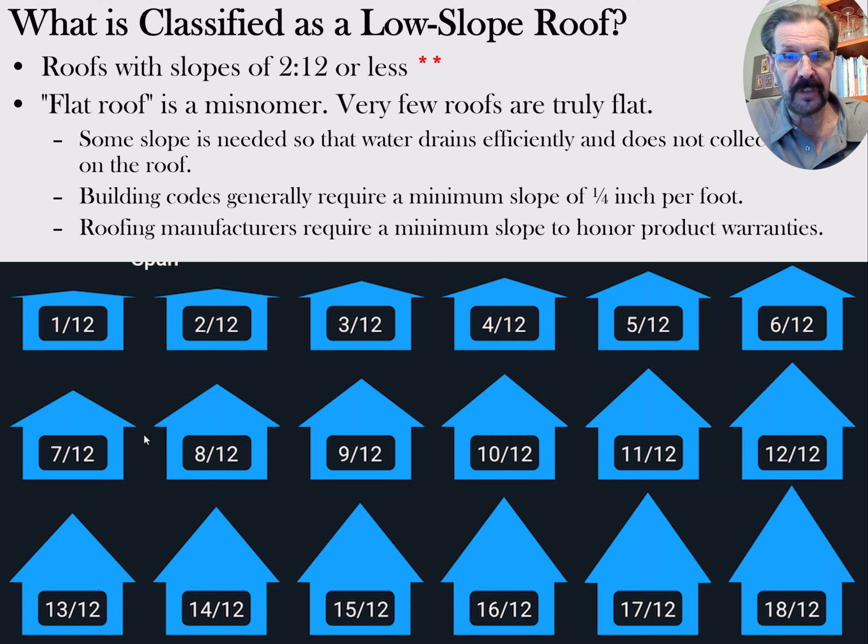Typically with shingle roofs on anything less than a 4:12 slope, you do have leakage. Unless you just put in a good solid single-ply roofing down as your really, really good membrane for your underlayment, which is not really cost-effective to do it that way. And then you end up putting the shingles on top for decoration, but you're really relying on the roofing membrane underneath. So this picture is showing you kind of what the slopes would look like, the profile of the slopes of roofs on a 1:12, 2:12, 3:12. Until you get to 4:12, you really shouldn't be using shingles because the water will back up underneath the shingles.